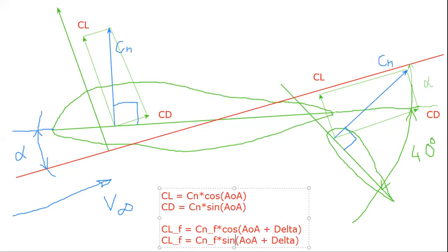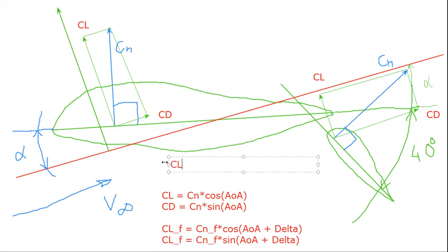So we have this formula, and the total lift equals CL airfoil plus CL of flap. So our task now is to obtain the CN vector and convert our array of data into a single value. This we do in MATLAB using the integration function trapz.